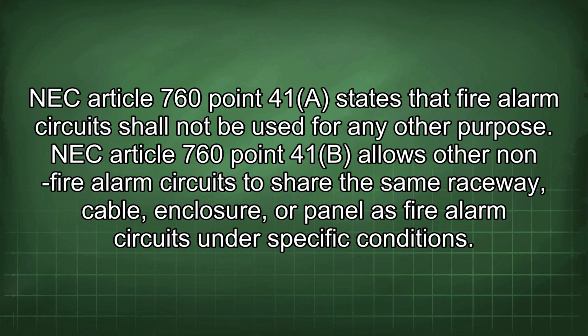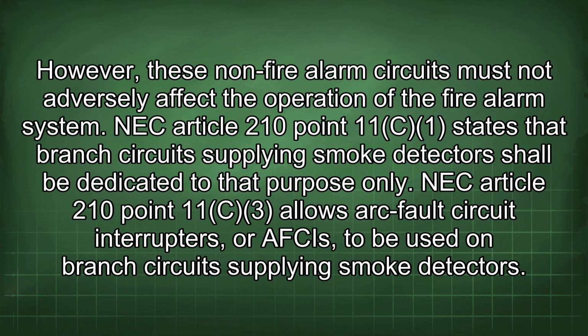NEC 760.41(b) allows other non-fire alarm circuits to share the same raceway, cable, enclosure, or panel as fire alarm circuits under specific conditions. However, these non-fire alarm circuits must not adversely affect the operation of the fire alarm system. NEC Article 210.11 currently states that branch circuits supplying smoke detectors shall be dedicated to that purpose only. NEC Article 210.11(c)(3) allows arc fault circuit interrupters, or AFCIs, to be used on branch circuits supplying smoke detectors.